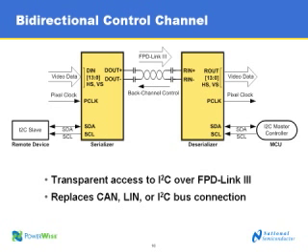So the I2C information comes in through the I2C port, as you can see on the deserializer, and then the GPIO data will come in on a separate pin on the deserializer, and that's all effectively packetized and sent over the low-speed back channel. So that GPIO is basically guaranteed. It's guaranteed, yeah. It runs regardless of whether the I2C is being driven or not. The GPIO channel is always free and available. Okay. That's a good question.